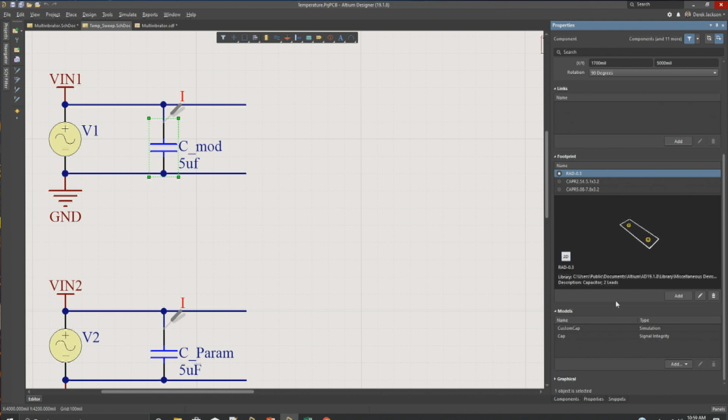So in Altium, we've done our best to support the PSpice variations of the syntax. Although, if you go into 20 with ngSpice, the PSpice support is not as heavy as it was in Altium Designer, so some things might not work as well. But the next phase of the simulation in 20 with the ngSpice implementation will be PSpice model support.